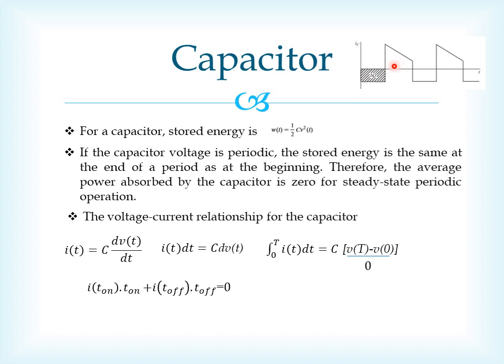And this is why we have used this expression to calculate the value of capacitor in the derivations. So just remember the current time balance in the case of capacitor and voltage time balance in the case of inductor, and this is the basis of why we have used IC average equals 0 in all the waveforms.